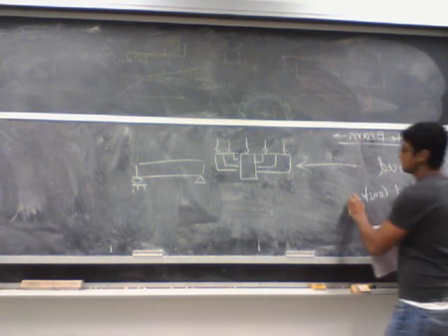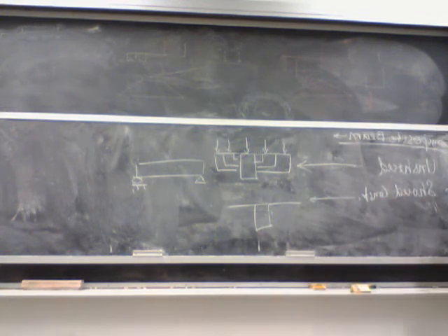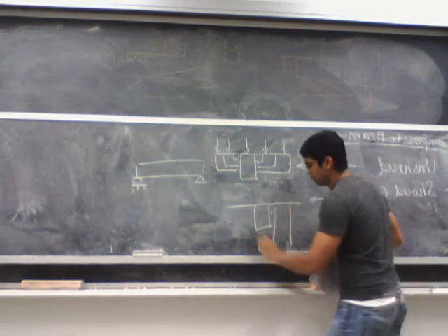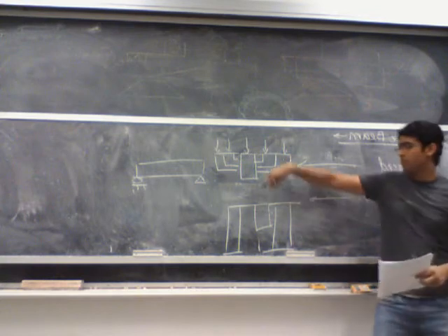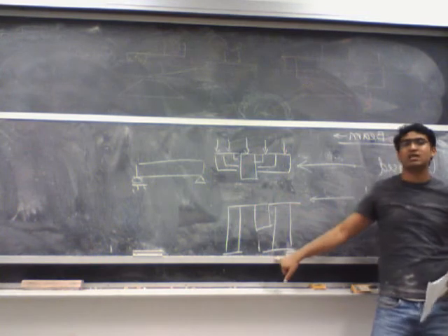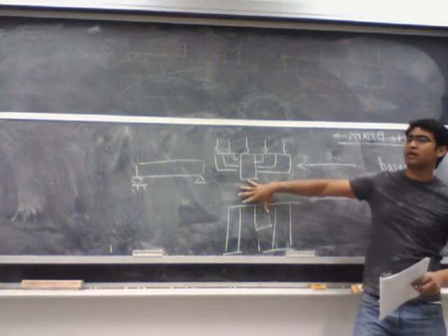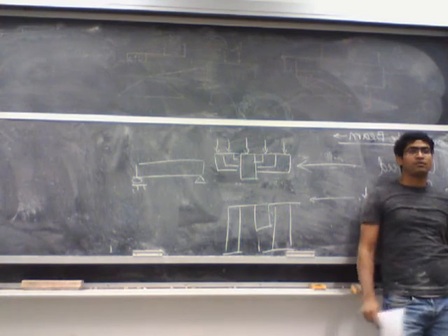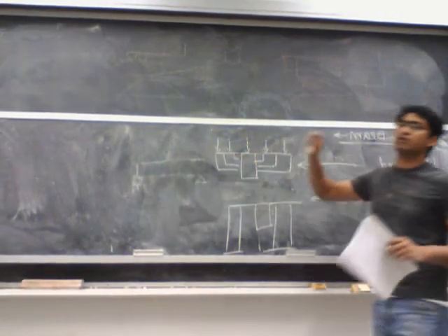In case of a shored construction, you still have your girder and your formworks for the slab. But the difference is that the formwork is not connected to the girder itself. It's seated on the surface. So if I put some weight on this formwork, instead of getting transferred to the girder, it gets transferred somewhere else. In a shored construction, when I pour my concrete, my girder doesn't see any increase in load.